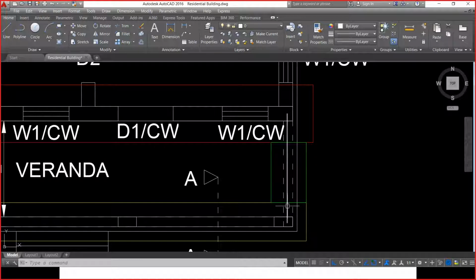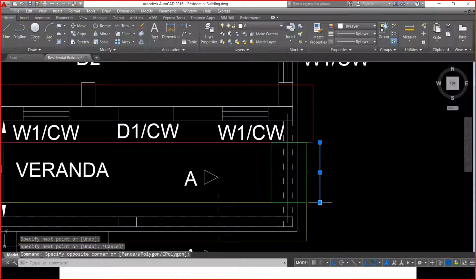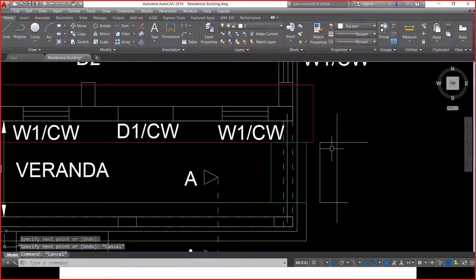Similarly, at the other end also, I have already done the excavation. I just need the distance from this point to this point. I'm going to draw it here. I want length calculation for only this one, but I already have the length calculation for this one. How to do the deduction? Just deduct this portion, deduct this portion. Anything above this line you deduct it, anything below this line you deduct it. Between these two lines you have to get the actual length. So how to get that?